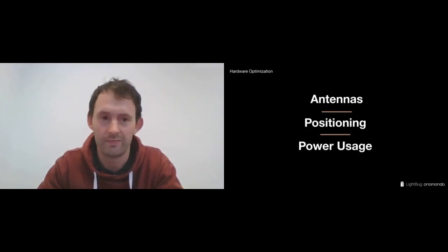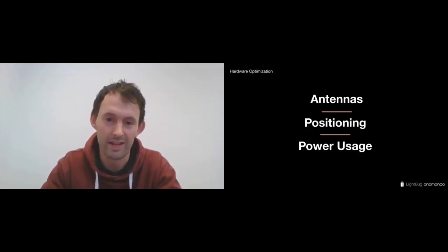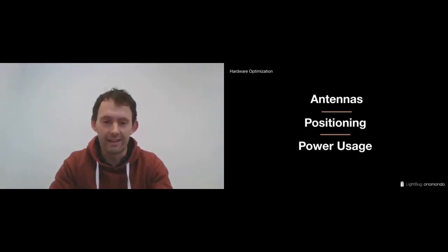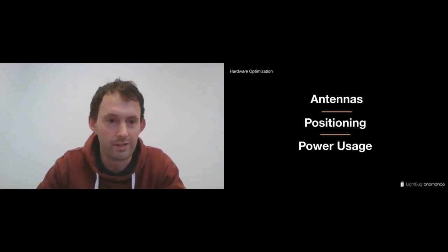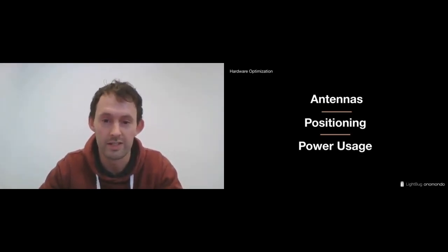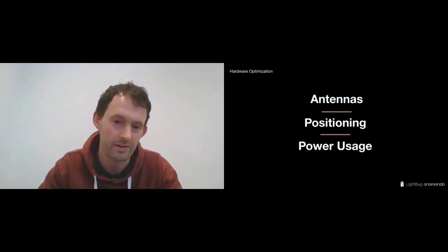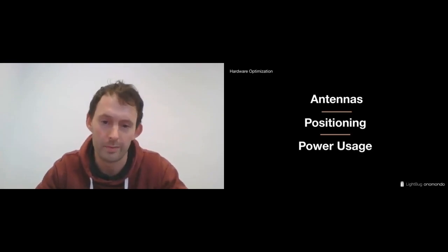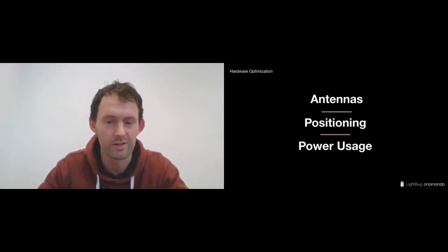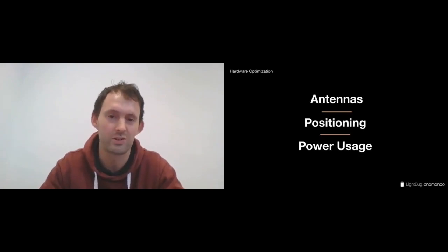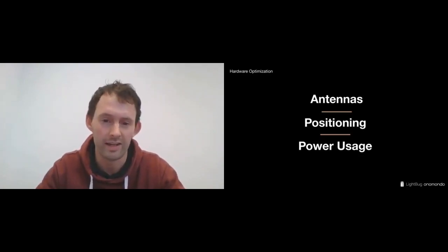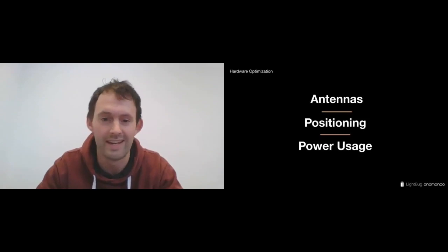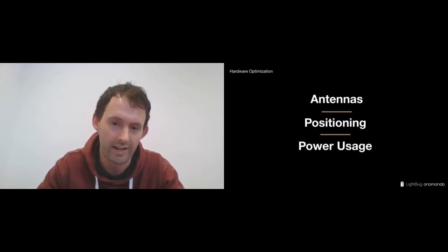And we tend to say, obviously, the bigger the better. I've said that, but when it comes to using it, we appreciate that that's not always the case. Sometimes devices need to be hidden for them to serve their purpose. They're anti-theft devices, they're deterrents, or they need to fit within a certain flight case. At which point we start looking at how we optimize positioning. And again, some fairly obvious, top-level stuff is that devices don't like being near metal. If you put the antenna or a device near, not even in a metal box, but near a big metal object, you're going to degrade your performance.